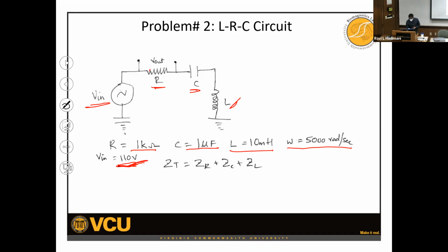So this is a simple circuit with one loop, right? It's one loop. So what do you do in one loop? You have to apply KVL, Kirchhoff's voltage law, right? This is your loop. So that means you have 3 components and an AC power source, right? So you can either do a voltage divider, so this is a voltage divider with this here and the remaining to here, or you can do the KVL.